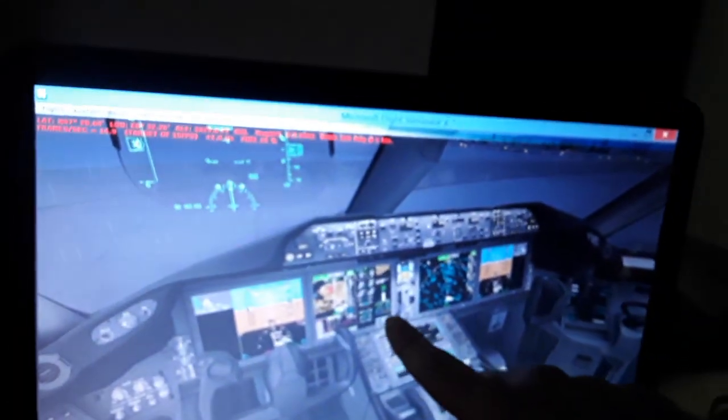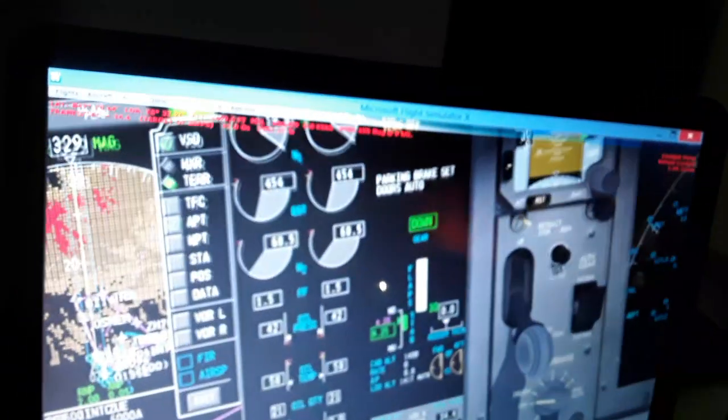Also, as we fly the aircraft at higher altitudes, we have freezing temperatures. Most jet aircraft have the recirculation system from the left and right wing tanks and the center tank to the engine components. This is controlled automatically by the FADEC to heat up the fuel by ducting heat from the engine components and cooling down the engines. We do the same for the lubricant and the oil. As we fly, the fuel recirculation system is automatic. So you can monitor here the temperature of the fuel. Later I will also show you in the displays.